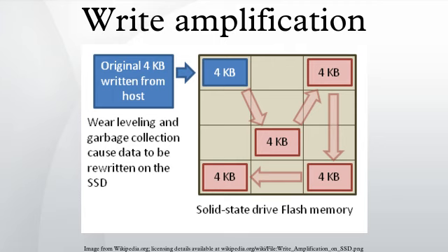Due to the way flash works, much larger portions of flash must be erased and rewritten than actually required by the amount of new data. This multiplying effect increases the number of writes required over the life of the SSD, which shortens the time it can reliably operate. The increased writes also consume bandwidth to the flash memory, which mainly reduces random write performance to the SSD. Many factors will affect the write amplification of an SSD. Some can be controlled by the user and some are a direct result of the data written to and usage of the SSD.